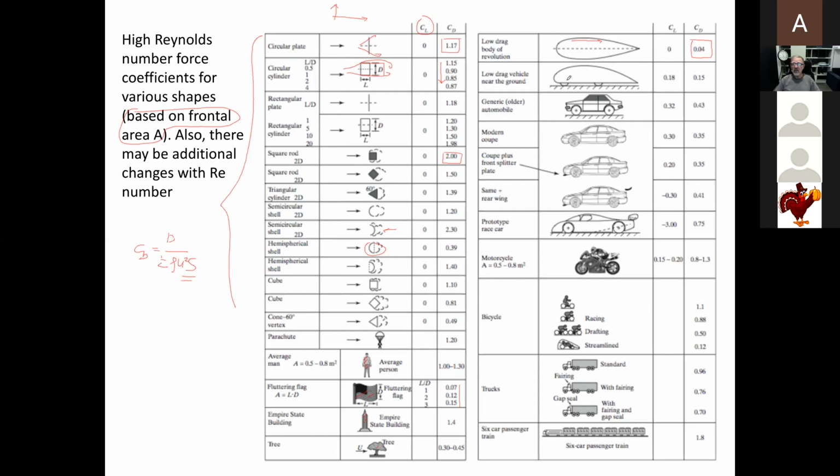Now, if you make it more like an airfoil shape, but very streamlined, and maybe have tiny little wheels, and I'm trying to go to automotive aerodynamics a little bit here, then you can have a drag coefficient of maybe close to 0.2 and a lift coefficient of 0.15. Now, you go back to the 70s and 80s, they have those really boxy cars, and then they actually had a lift coefficient.